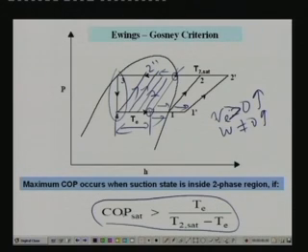And what is COP_sat here? COP_sat is the COP of the saturation cycle 1, 2, 3, 4. And what is T2_sat? T2_sat, as you can see here, is nothing but the compressor exit temperature when the compressor inlet is on the saturated vapor line. So what we have to do is simply take the saturated cycle, find the COP of the saturated cycle for any given refrigerant from the enthalpy values, then find the compressor exit temperature T2_sat, and then find this value. If you find that this is greater than this, the maximum occurs inside and superheating is bad from the COP point of view. Let me show this with an example.